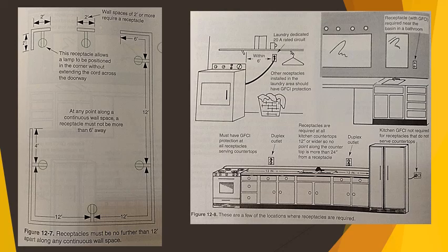Locate the receptacles close to the ends of large wall spaces to avoid concealment by sofas or other large pieces of furniture. Receptacle outlets should be placed 12 to 15 inches above the floor line. Placing the receptacles at height of 15 inches allows for easier access. A receptacle outlet must be installed at each island or peninsular type countertop that is 20